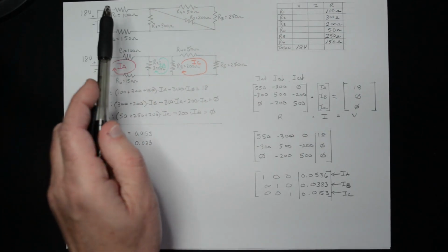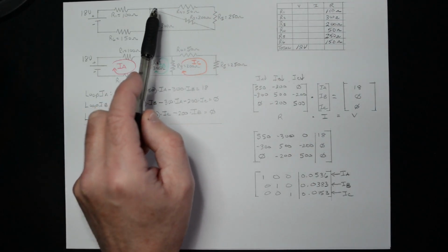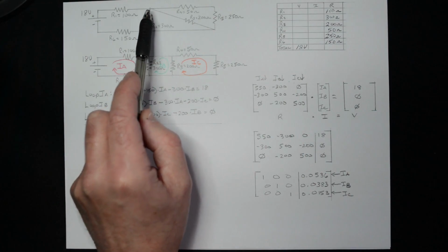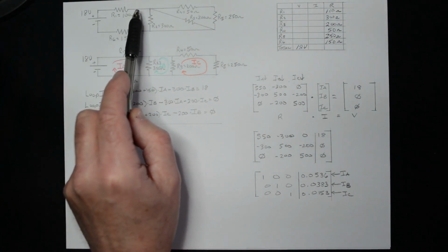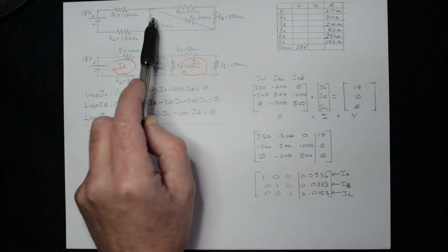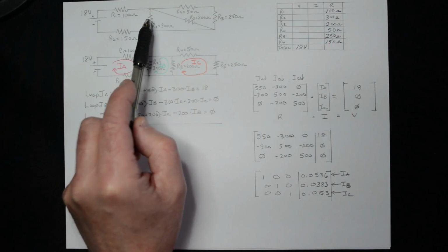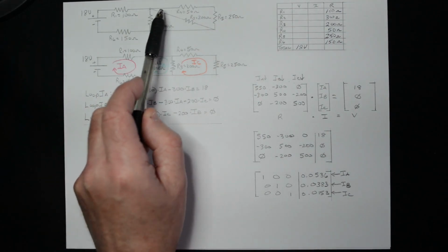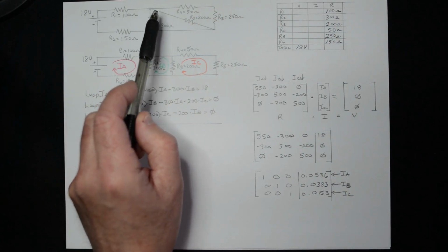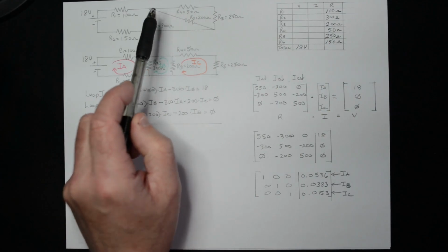The point I show to you is take this conductor here on R3, this end of R3. You can move it anywhere you want. Don't go past a point. In this case, you could go past a point, but it would confuse the numbering convention, and you could do it, and as long as you kept track of everything, it would be fine. But for simplicity's sake, don't go past a point and never go past a control. Now, we don't have any controls, switches, push buttons, etc. You can't do that either.